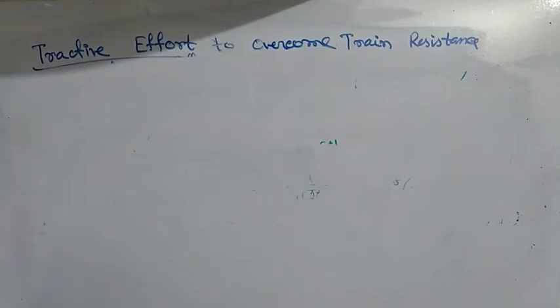Now, since head resistance is about 10 times the suction resistance, the shape of the front carriage is very important in reducing the wind resistance. Wind resistance due to the length of the train is due to air friction on the sides and the underside of the train, and this is sometimes termed skin friction. The pressure drag is found to be far less than the frictional drag for long trains. It is found that endeavor to diminish the pressure drag is not so effective for reduction of total drag.